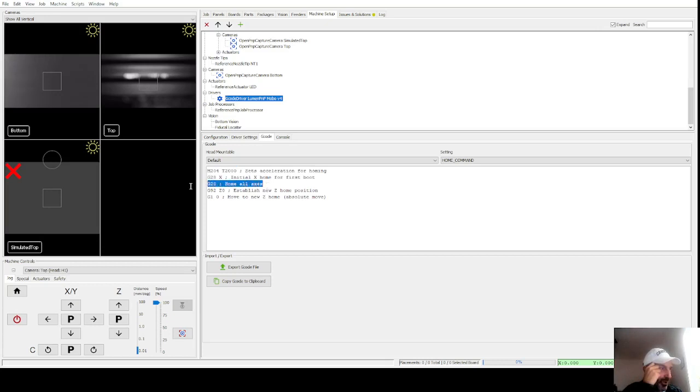Then we do a normal home, but then some stuff that I added based on the suggestions from the OpenPnP mailing list is to establish a new Z0 after it homes. It's going to establish, I think, Z31.5. And then we're going to go to 0 after that. And the interesting thing is when we go to 0, this DRO in the bottom right side will not say 0 if we didn't actually set the home to 0. So yeah, what did I mean by that?